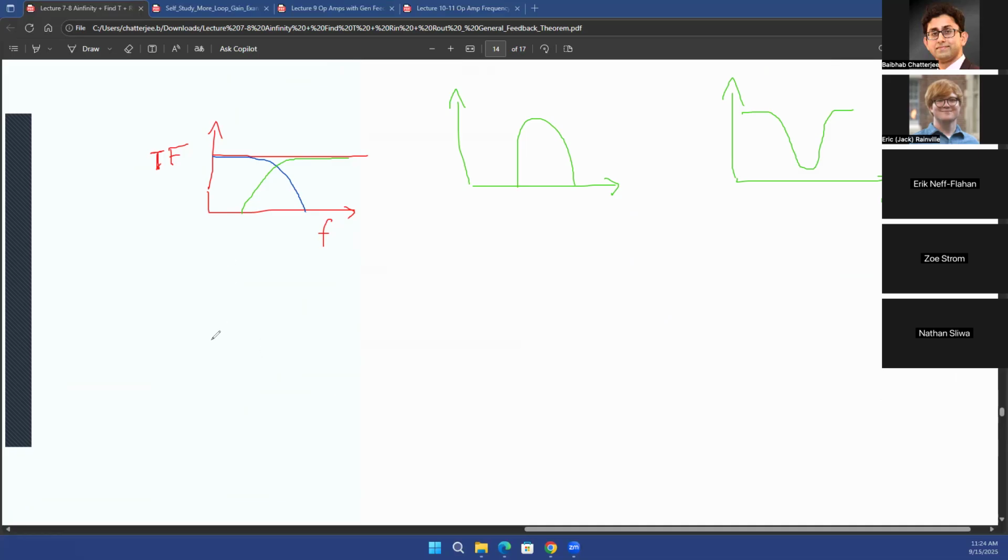So let's just first start with calculating what would be the transfer function if you have a simple circuit containing a resistance and a capacitance. So let's say you have your input connected on the left side. Let me call this Vi, and your output is Vo, right? I'm writing Vi and Vo because I just don't want to write too many characters right now. What you're interested in is just the ratio of Vo over Vi, right? And this is resistance R and the capacitance is C.